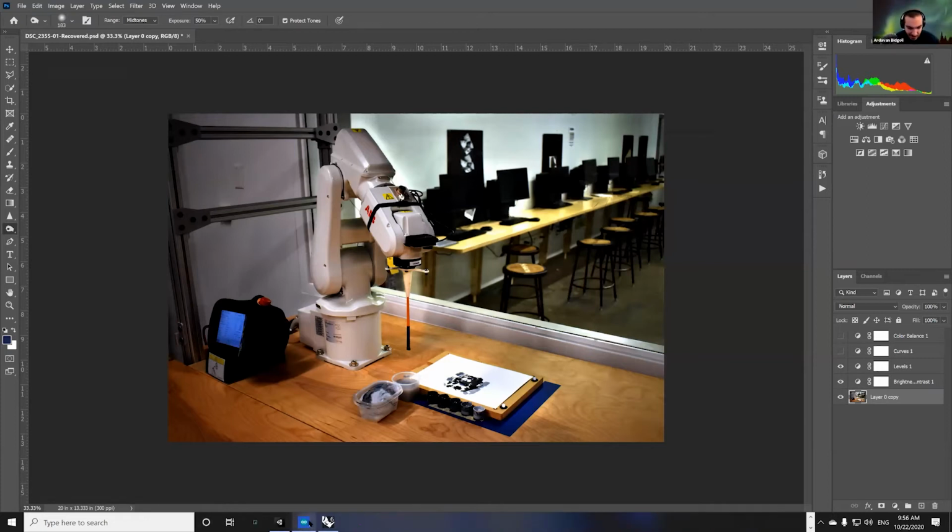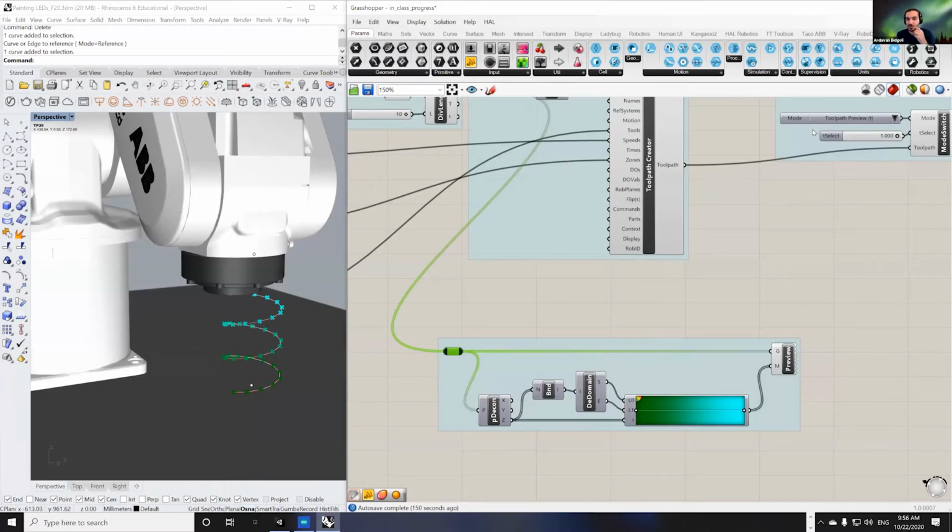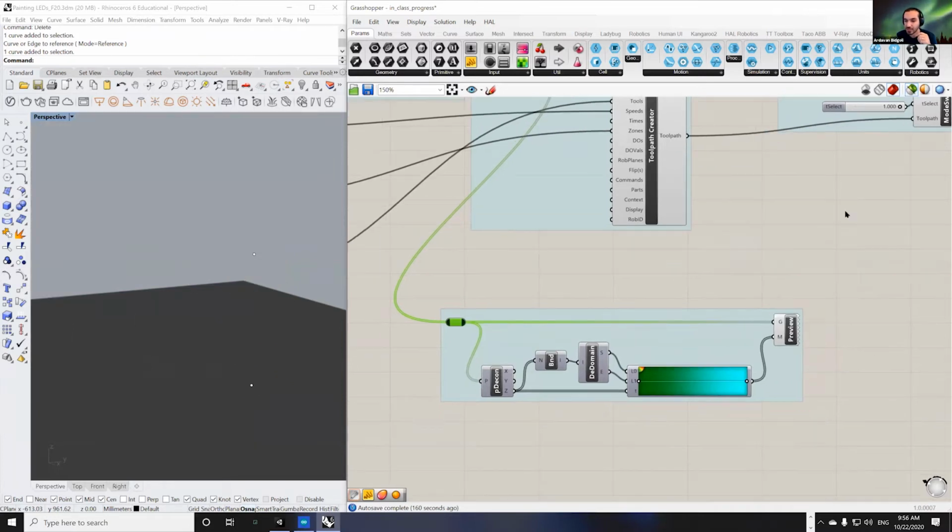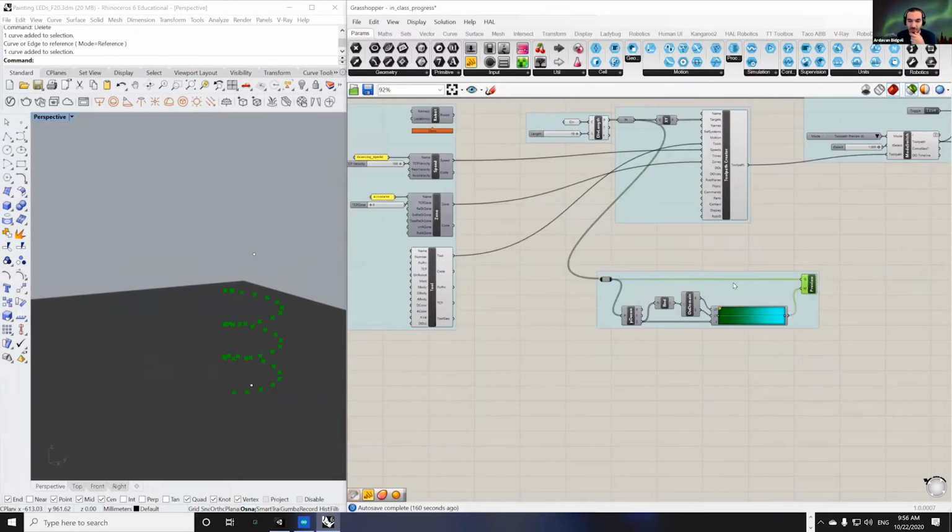So let's go back to here. Okay, good. The option that I was talking about is actually this one here. If you use this option, Grasshopper is only going to show you the objects that you have selected actively, but it doesn't work when you are working with custom preview, because whenever you select something in Grasshopper and ask it to show it to you, it's going to show it as green, and whenever it's green, you cannot see the real color.